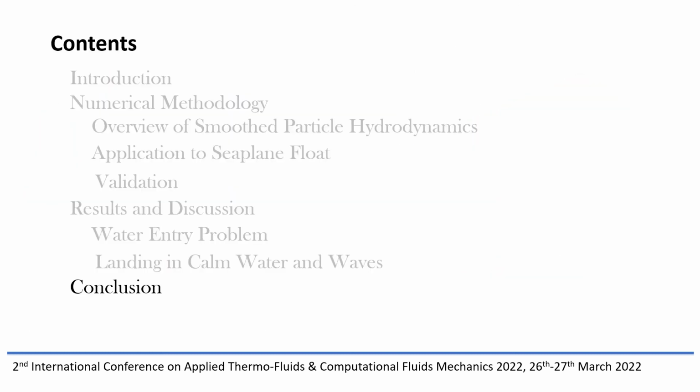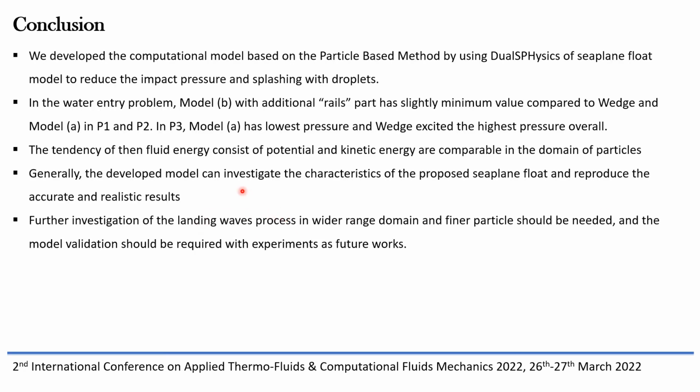And the last one is the conclusion of this study. We developed the computational model based on the particle-based method, using DualSPHysics, of the seaplane float model to reduce the impact pressure and splashing with droplets. In the water entry problem, model B with the additional rail part has a slightly lower value compared to the wedge and model A at P1 and P2. But at P3, model A has the lowest pressure and the wedge exhibited the highest pressure overall.